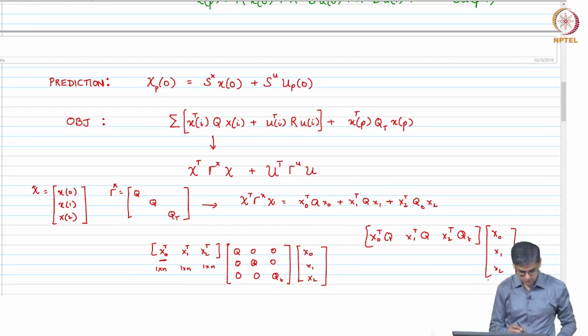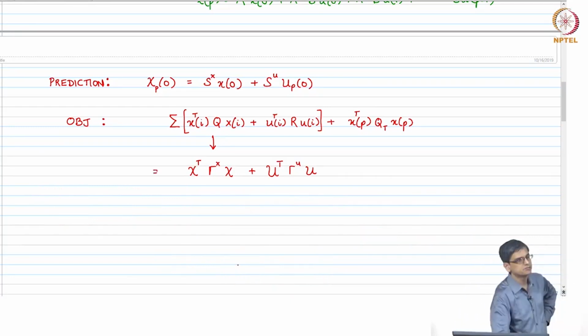Okay, clear? So, this is how this works. Regulation means starting with any arbitrary x0, you determine the control action so that the system goes to origin in finite amount of time. That is the question that controllability reachability answers, whether or not you can.